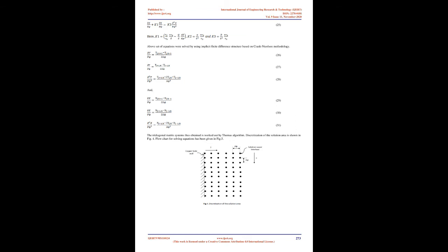under the assumption that the falling film completely wets the tube wall. Integrating the velocity profile Equation 7 from 0 to the film thickness over the horizontal tube, it is derived as Equation 10. Differentiating Equation 10 with respect to x, the rate of change of film thickness in the x direction becomes Equation 11. Heat transfer through conduction at the copper tube wall is Equation 12. The overall heat transfer coefficient, U, in Equation 12, is defined as Equation 13.